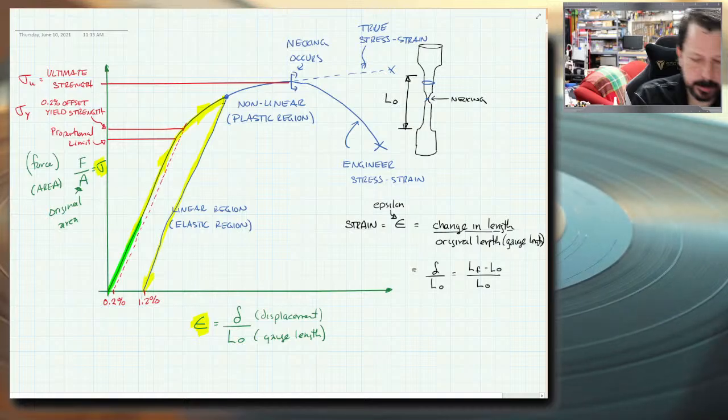So sometimes you intentionally make things stronger by stretching them, entering their plastic region, letting go so you don't fracture them, and then the next time you load them, they have a higher yield strength. That's usually not part of your machine. That's before you do that. I guess a specific example might be bolts. Sometimes you do yield bolts so that they work harden a little bit.